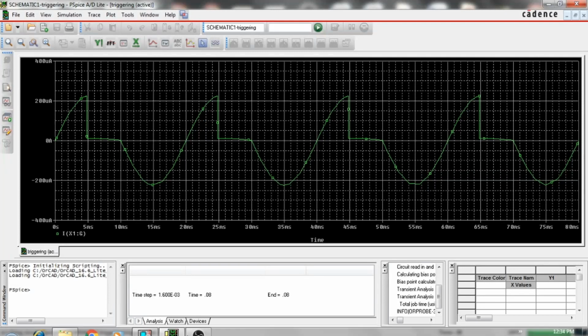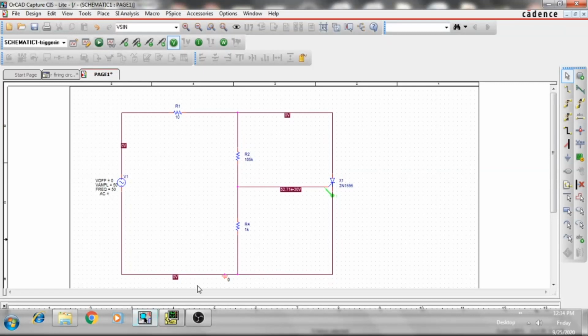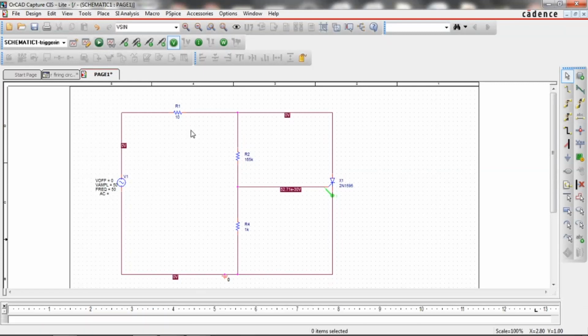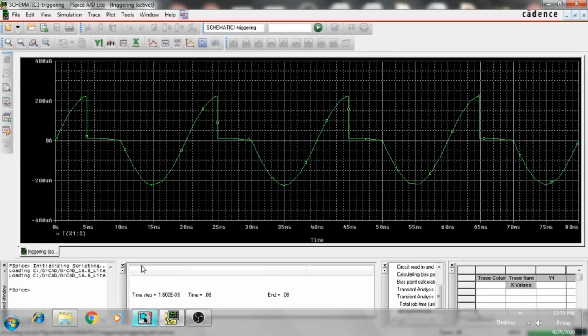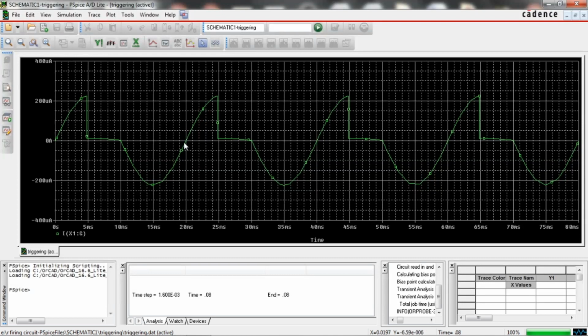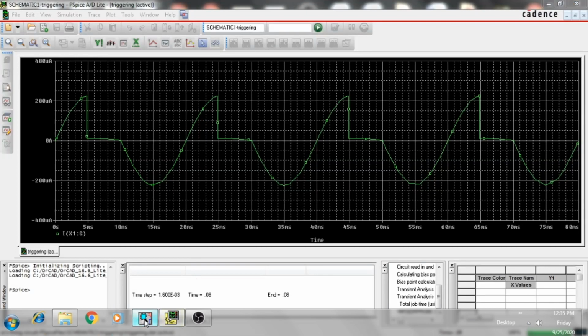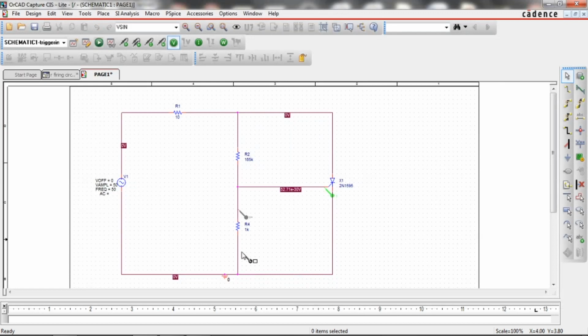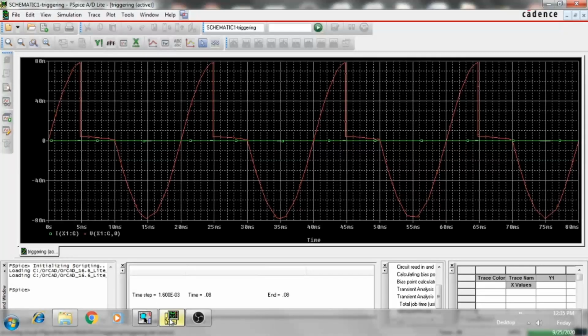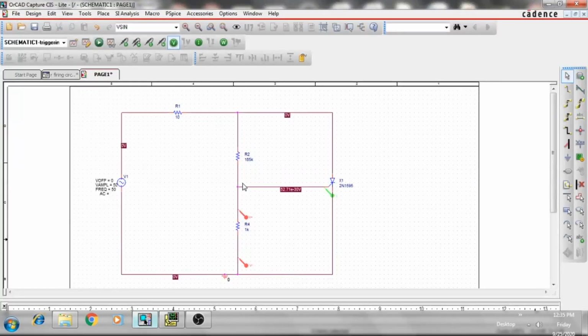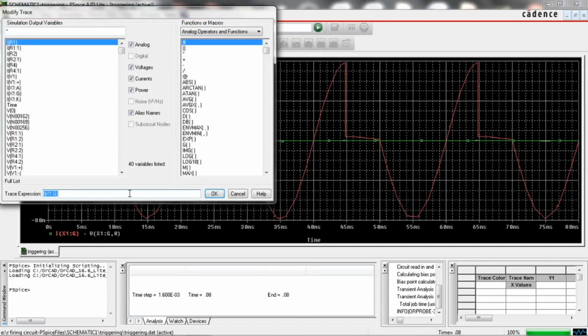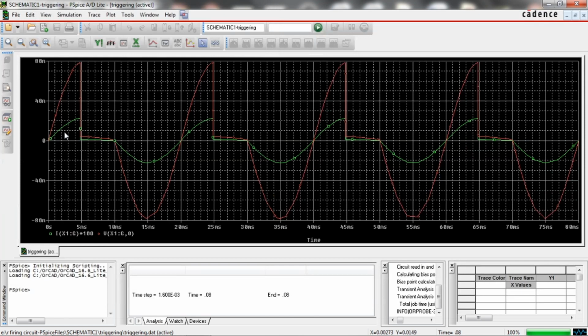But in the negative half of the cycle, what happens? You can see here in the negative half cycle, the SCR is off, so current moves in this direction. Some amount of current moves in this direction because there is a resistance here. That's the reason some current also moves towards the gate terminal in the negative half cycle. If you check the voltage developed across resistance R during that time, the current is very small, so it is not visible. So we magnify it by multiplying by 100, and now it is visible.